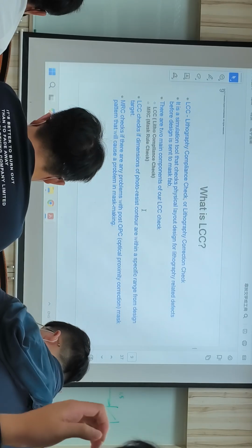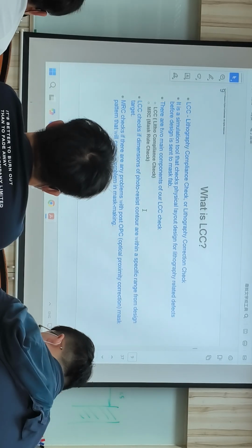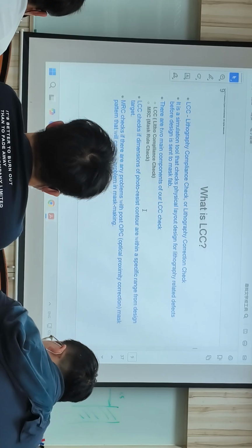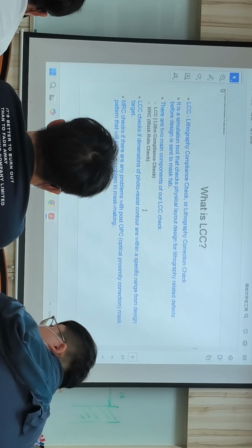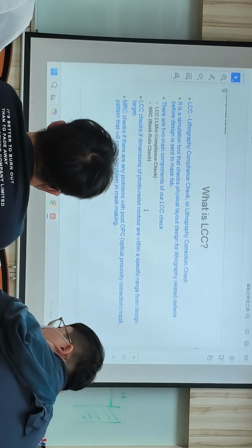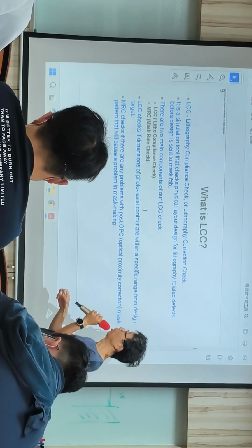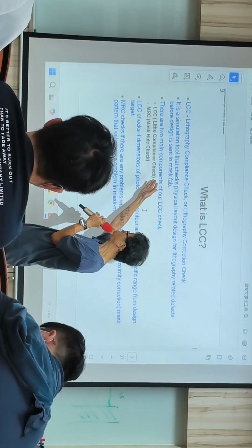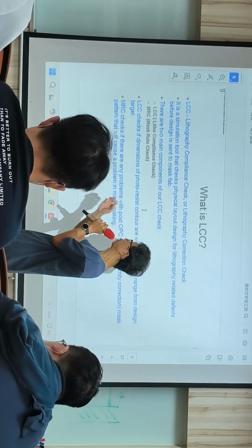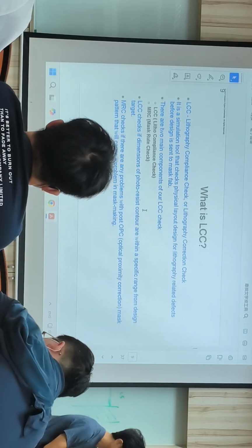Okay. And the next one is LCC, which is short for lithography compliance check. This is a simulation tool to check the layout, to check the related defects before putting it to the mask. There are two things to check. One is basically the wafer litho compliance check, and the other is a mask rule check. So one is LCC and one is MRC.